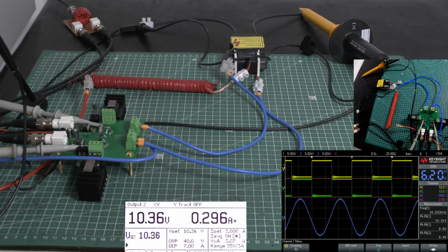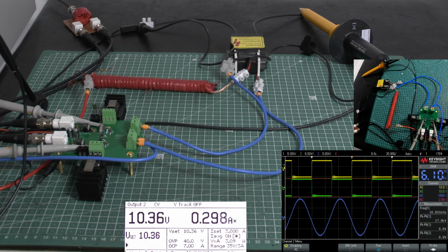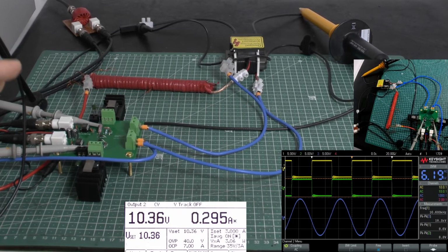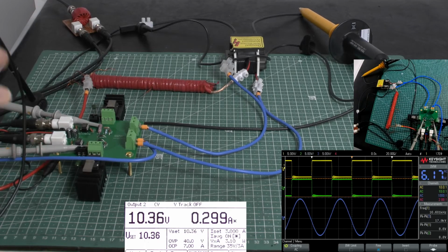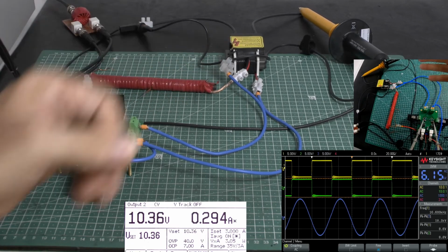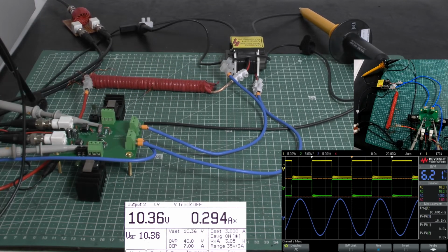The ratio needs to be ideal. Most of the time I used only 5 or 6 volt and I didn't see any big difference. But now, going into very close testing and analysis of power consumption, I can say that if we have a higher voltage on the gate side, we are actually achieving a better current transition over to our load.